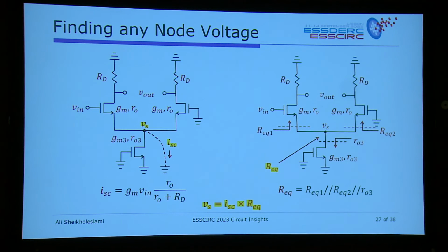Let me now go to a little bit more complicated circuit. This is a quiz question on my exam usually. First time, they've seen the diff pair, they know how to solve the diff pair and find the voltage gain, but I just zero one of these so they can't use the differential or half circuit, make it zero, and I have Vin here, and I say find Vs. Find the voltage of this.